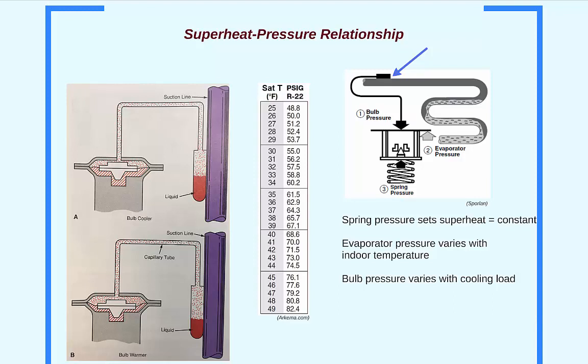The manufacturer installs R22 such that the refrigerant always operates in the liquid vapor region, meaning some of the refrigerant in the bulb is in liquid form and some remains in vapor form over all the operating conditions. The bulb temperature is the same temperature as the evaporator at the point it is measuring, which in this case would be at the discharge of the evaporator.